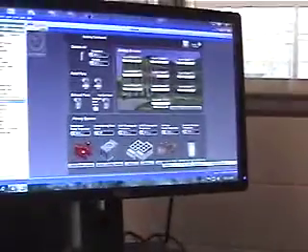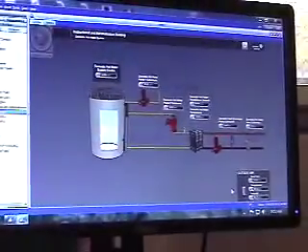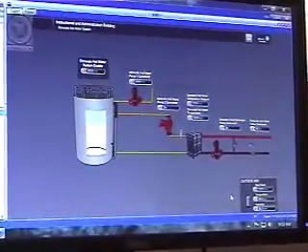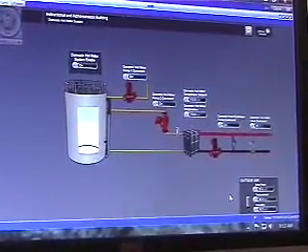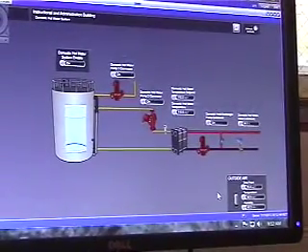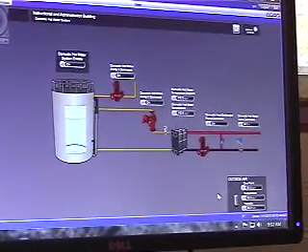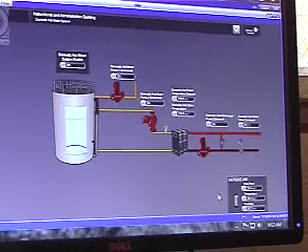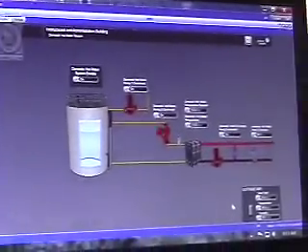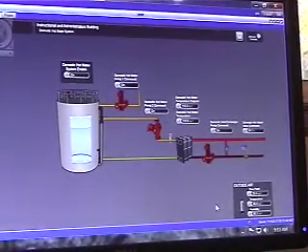All right, here we look at the domestic hot water system real quickly. Domestic hot water is fed off of those heat exchangers in that building, so that's why you pretty much need to leave those running. We talked about it a little bit with Daniel. I would almost say you'd want to leave the heat exchanger running all the time. You're going to have classes till probably 10, 11 o'clock at night. You start up again at 5, which doesn't give you a lot of time, and then you have to recuperate all the water in that tank. So I'd probably just allow the system to run.